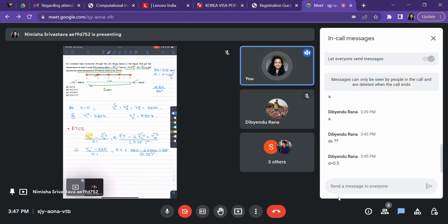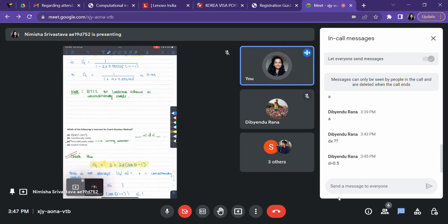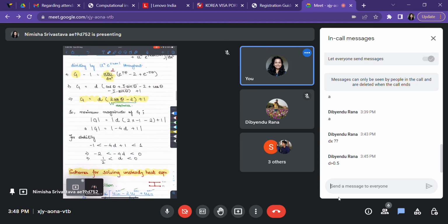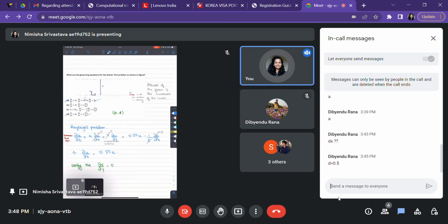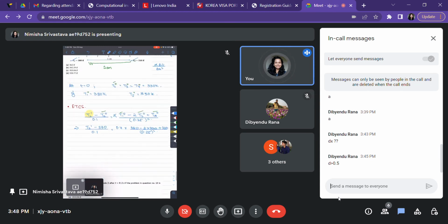So it's greater than 0.5 as noted. So it's not going to be stable, is it? Let's have a look at the stability criterion. It needs to be between 0 and half. Okay, no problem. But you anyway go ahead with the problem, compute the results, and then you'll get a practical feel of why this solution scheme is not right for your problem.